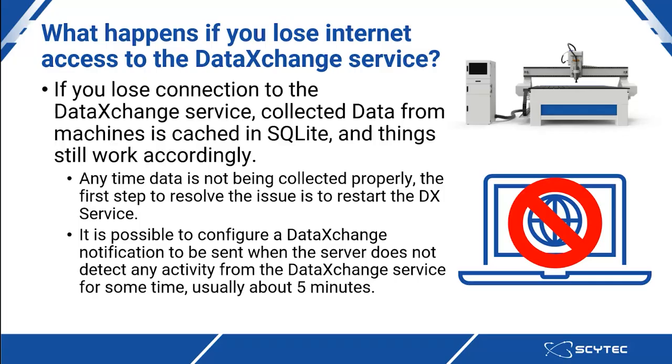Anytime that data is not being collected properly, the first step to resolve the issue is to restart the DataXchange service. It is possible to configure a DataXchange notification to be sent when the server does not detect any activity from the DataXchange service for some time, usually about 5 minutes. You can get a notification in either Microsoft Teams, text, or email alerting you that the DataXchange service has stopped communication and that you can go out and restart it.